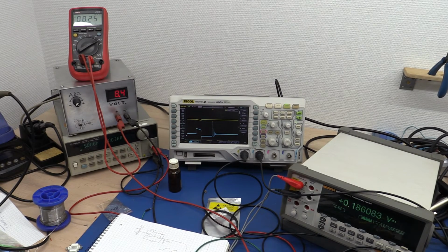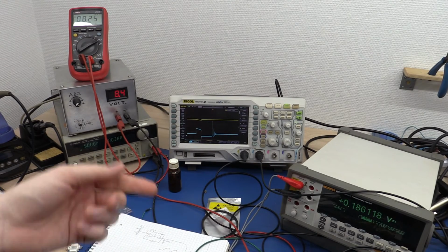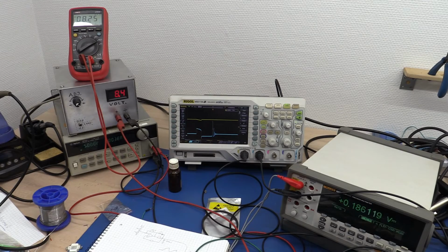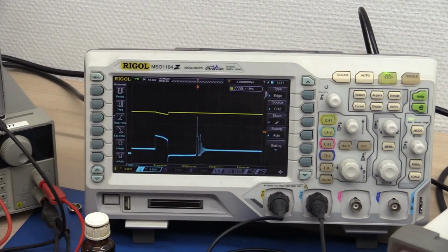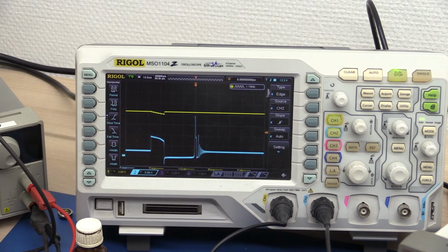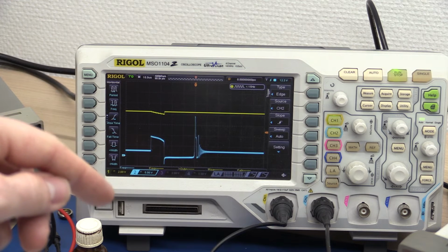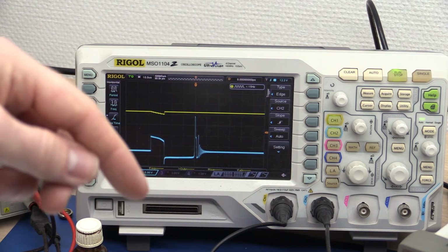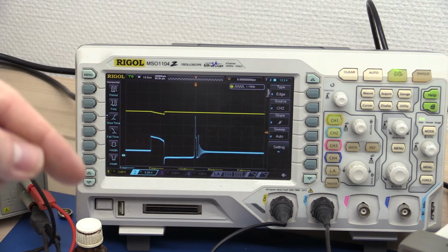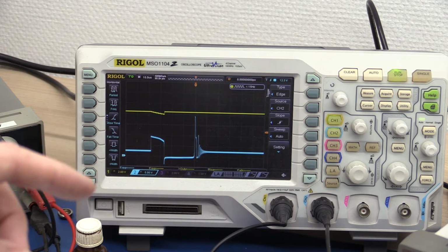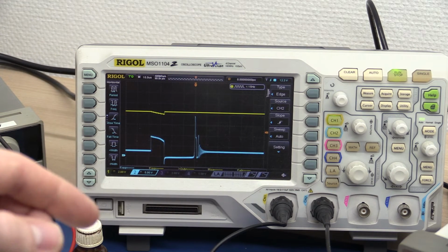which is not great, but it's better than a linear. Again, this circuit was really only just to play around. It wouldn't make sense to make your own. Just one of the things that contribute to the fairly low efficiency is, first of all, the DC resistance in the breadboard, and also losses in the transistor and the diode.